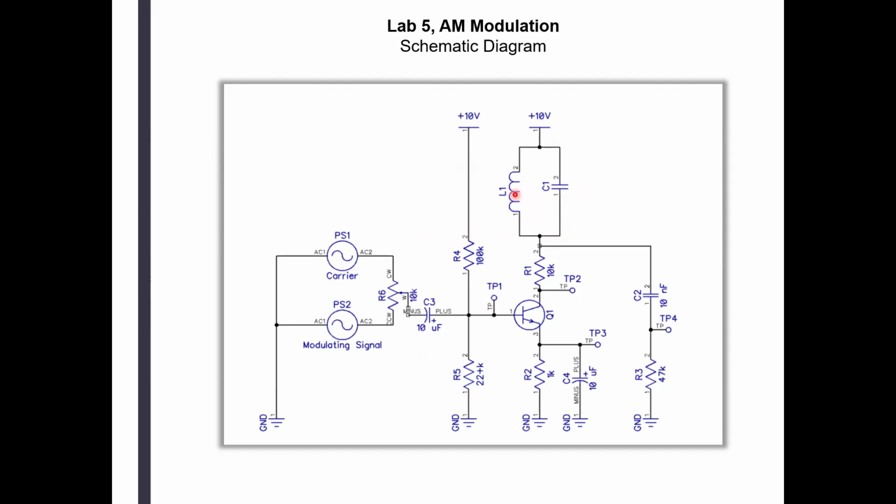So you're going to have to choose appropriate parts in order to accomplish the resonating frequency by request. And then you're going to set the function generator to that frequency. So this whole thing is going to just cook with gas. Other frequencies are going to be amplified too, but not as much. And we want this thing to be most efficient.